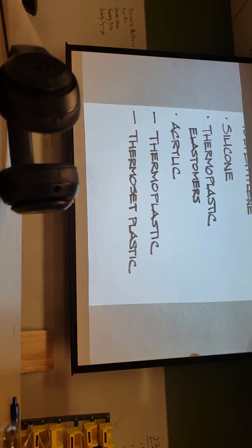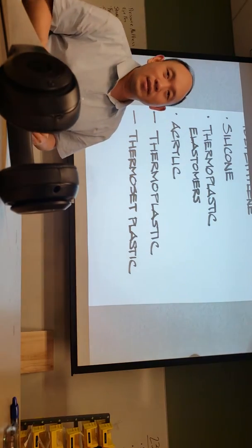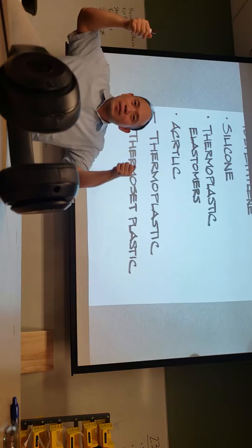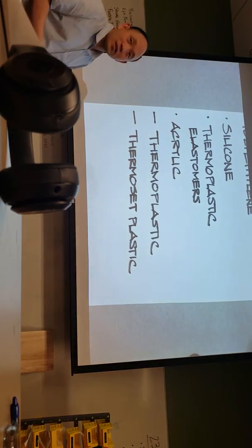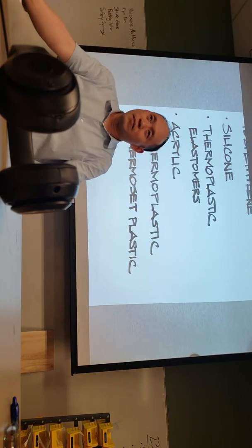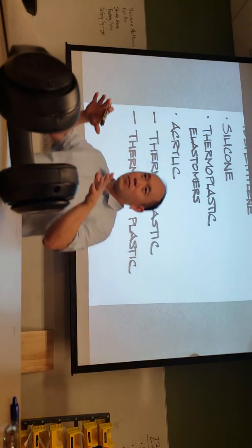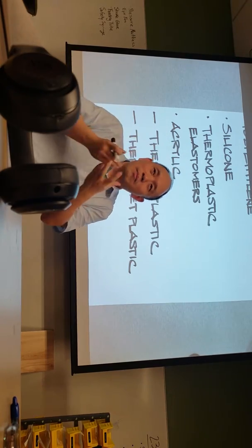Okay. Lastly, in terms of plastics in general, there are two types. Ones that react and form well under heat. Typically, those are things like polystyrene, styrene. Marty talked about vacuum forming. Do you guys remember that? Typically, thermoplastics are used for that because you can heat them up, they get really, really soft. You can form them over a mold, add vacuum, and then you get this form that stays after it cures. It doesn't deform, it doesn't crumple up, it doesn't melt.